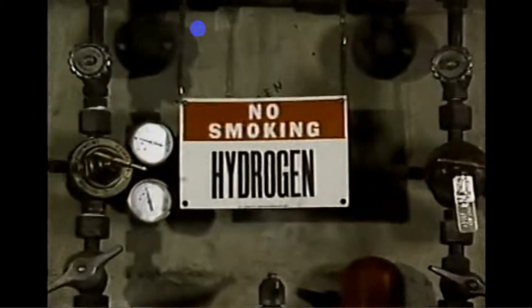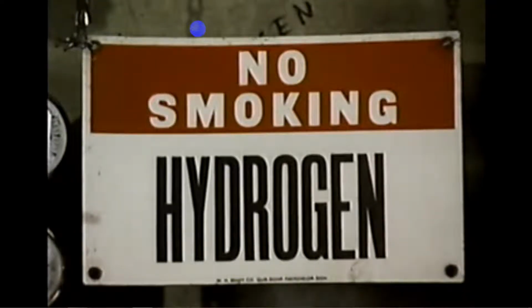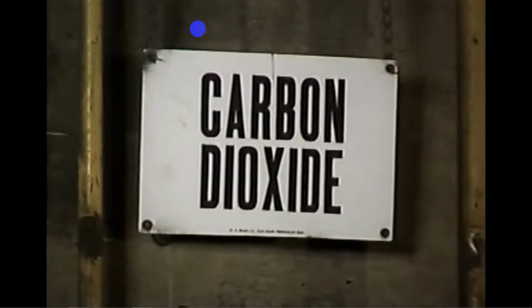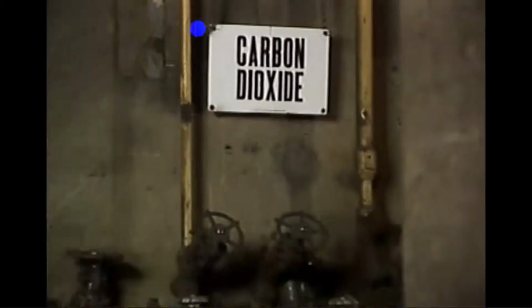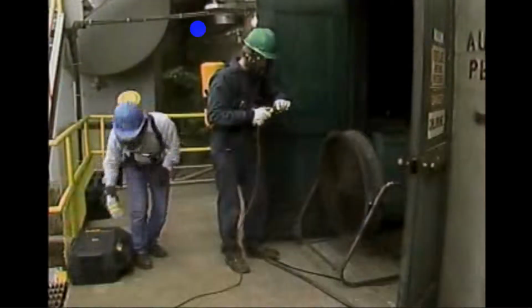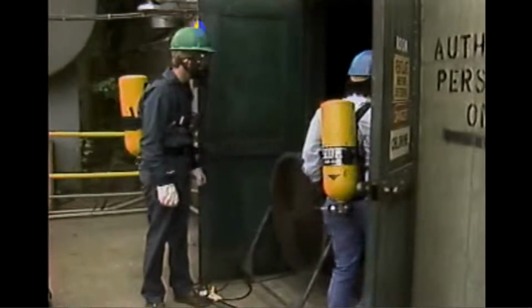Some compressed gases, such as hydrogen, may be flammable or explosive, so open flames and spark-producing equipment should never be used around these systems. Some compressed gas systems may contain gases that are toxic, and some may contain gases that displace air. In either case, these systems may make surrounding areas unsafe to breathe in if a leak occurs. Plant procedures may require the use of a respirator by anyone working around such systems.